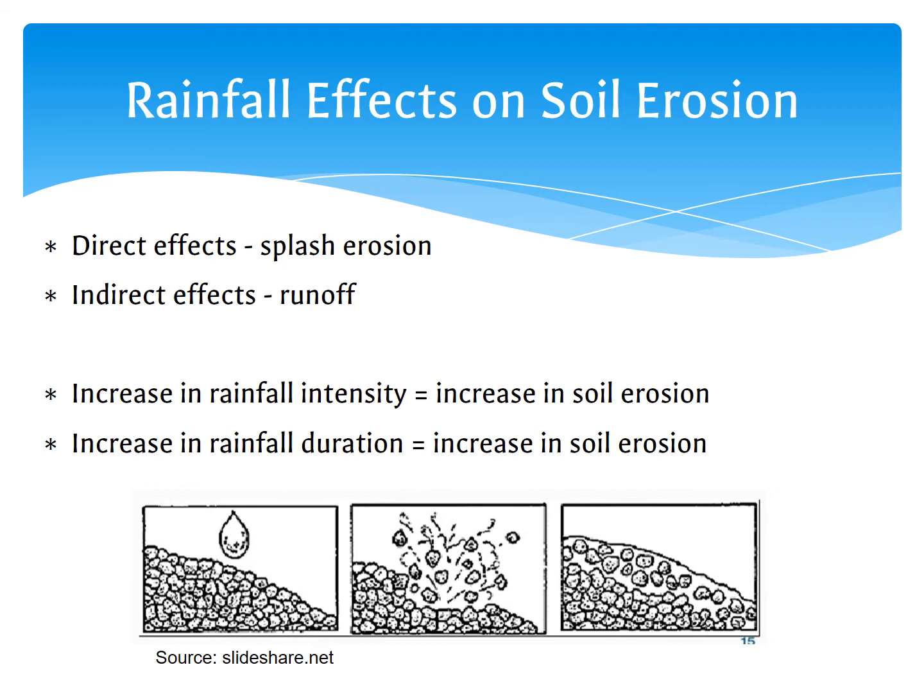Rainfall may also move soil indirectly by the means of runoff in rills or gullies. Rills are small gullies which can be removed through management techniques such as tillage, while this is not possible for gullies as they are too big. Gully erosion is commonly triggered or accelerated by land use change or extreme climatic events, which with climate change are becoming more common. The greater the intensity and duration of a rain event, the higher the erosion potential.